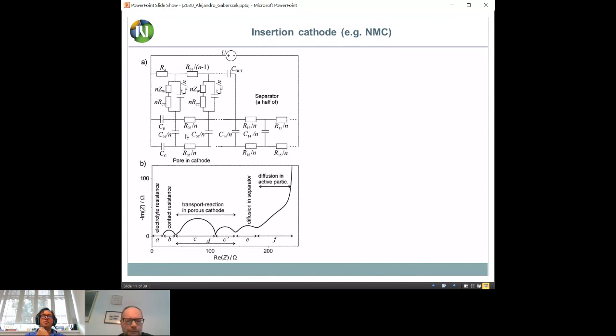But if you plot this, if you generate out of this scheme here that we have some general impedance spectrum, this is what you get below. So as you see, this is even much more complex than shown before by Abbas. So there are many more features, or specifically there are 6 features. So several quasi-arcs or arcs, some electrolyte resistance here, diffusion, and so on.